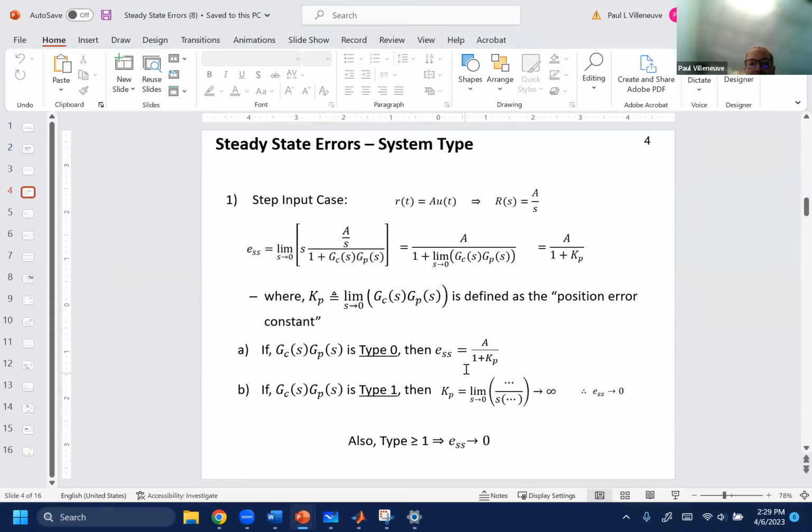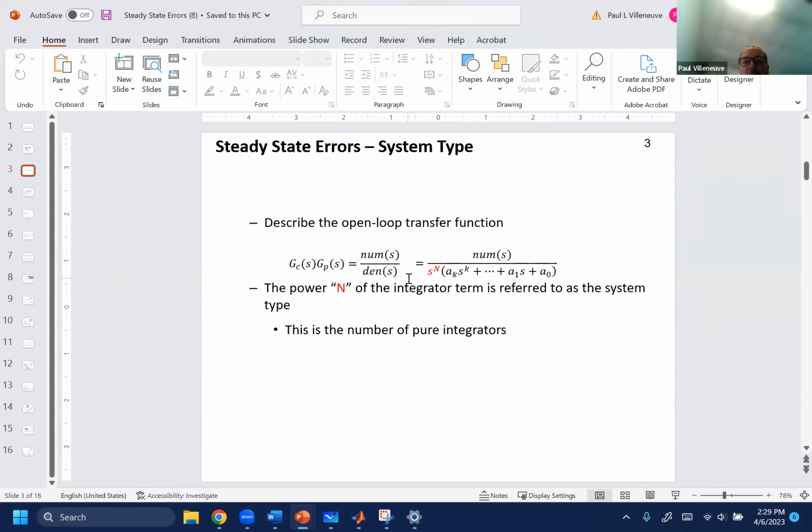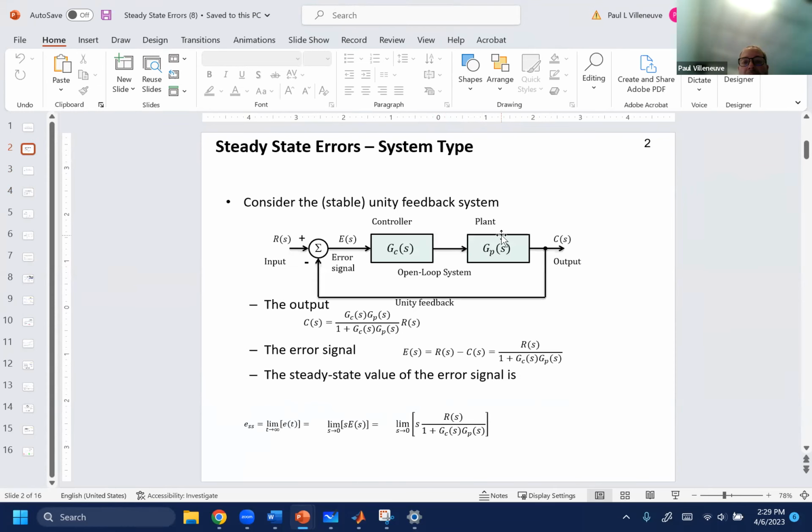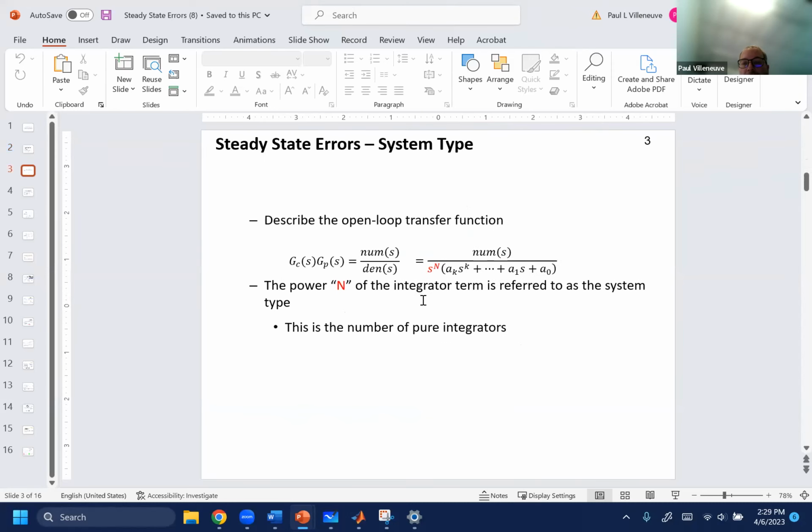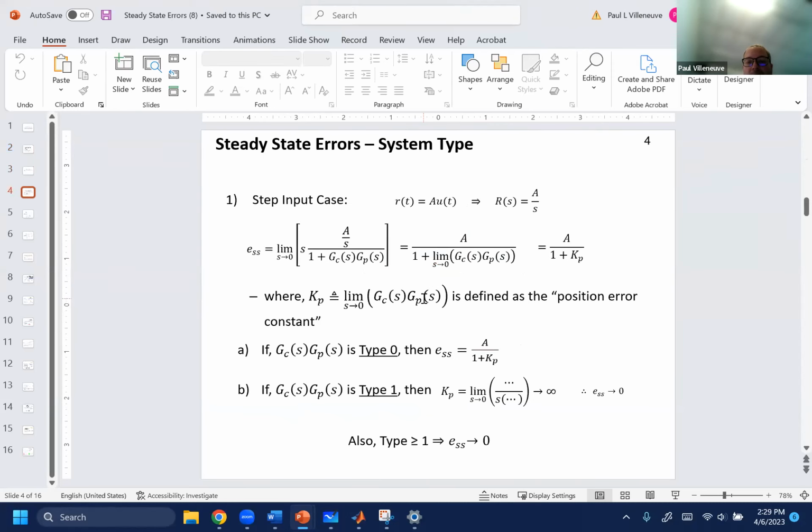And then eventually we came up with a concept of a K sub P, where you can see that we moved the error signal to just be around, in this case, because it was a unity feedback, our feed forward gain, just my controller and my plant. It doesn't include that G over 1 plus GH. Was this clear enough looking back, or do I need to add more clarity now?